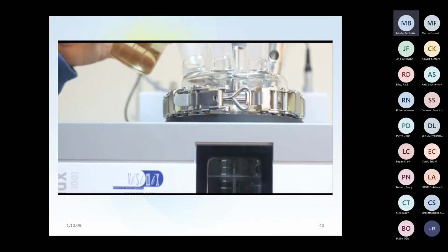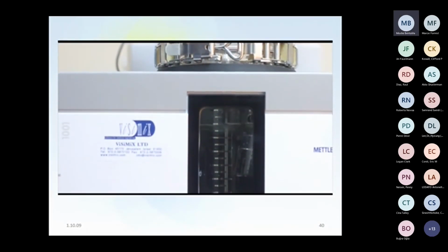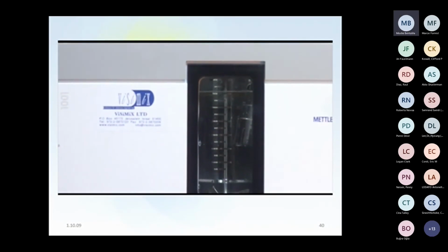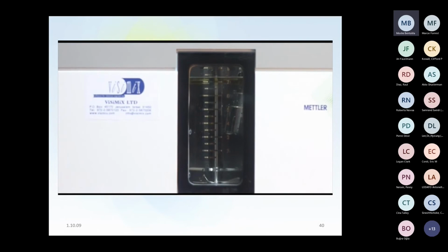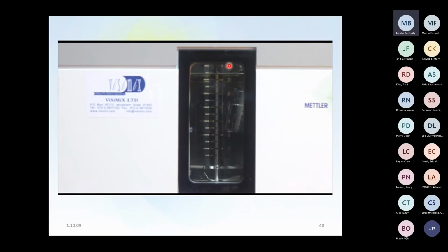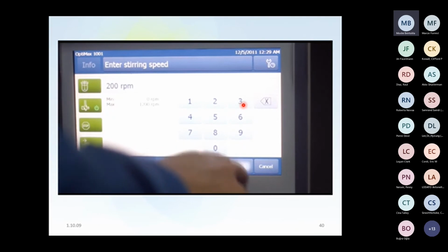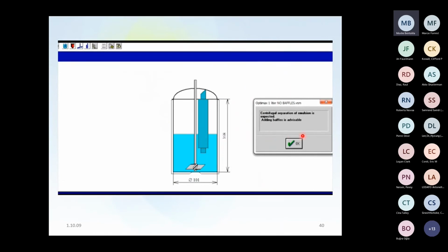If you're not doing this kind of experiments, and for instance, you feed kerosene in water in some equipment, you can think that maybe you are doing mixing, but once you are operating in different conditions, it will give you completely different results. You see here kerosene, okay, in the top, and you have here pitch paddle and rotor stator. If I raise the RPM to 200 RPM, you see here no connection between the phases. Kerosene up, water in the bottom. At 200, we have completely separate phases.